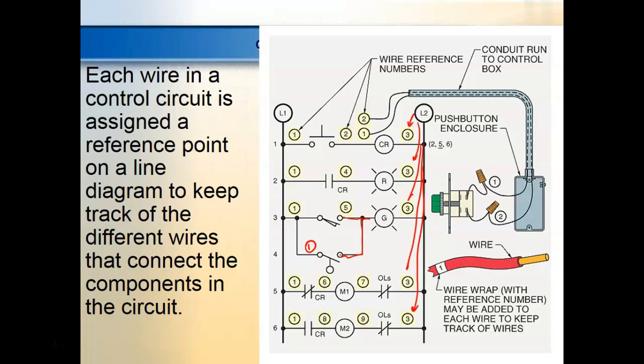The 70E standard has set 50 volts as the lethal voltage, even though it doesn't mean you can't get killed below 50 volts. It's just the standard they set. So as soon as you get above 50 volts, you have to start wearing special PPE, right? Anything below that, it depends on your company.